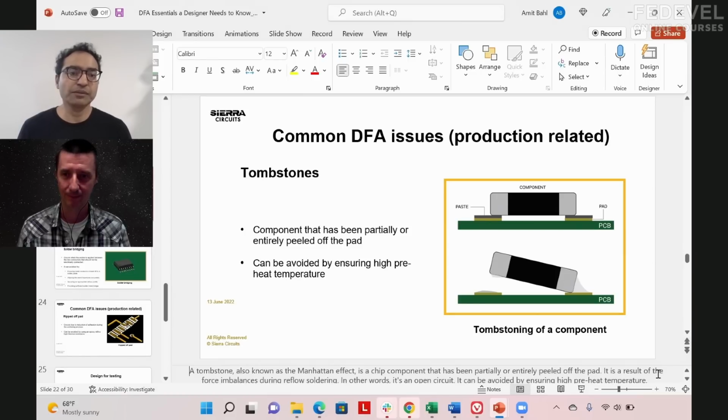Yes. So, for example, the via close to the pad or the via in the pad, people have been doing that forever, but the assembly houses will touch up and rework and add more solder, whatever solder has flowed or wicked into the hole, they'll add more solder and kind of fix the problem. In production, that's really not feasible. And so that type of thing should be caught at the time of product development.